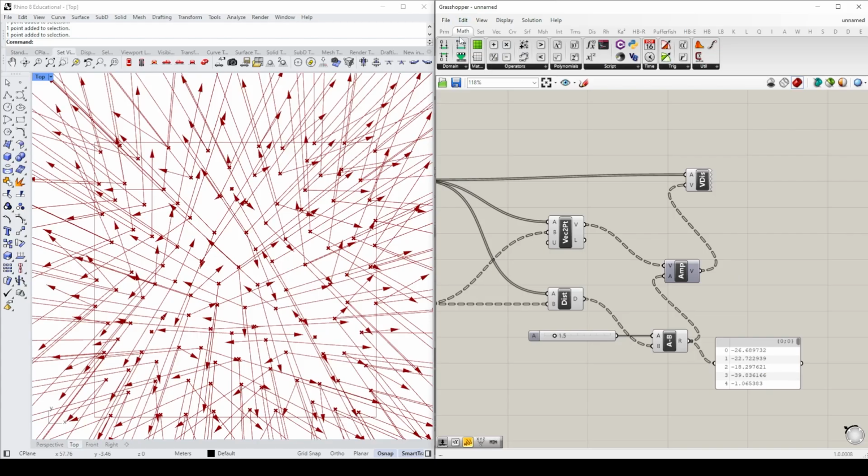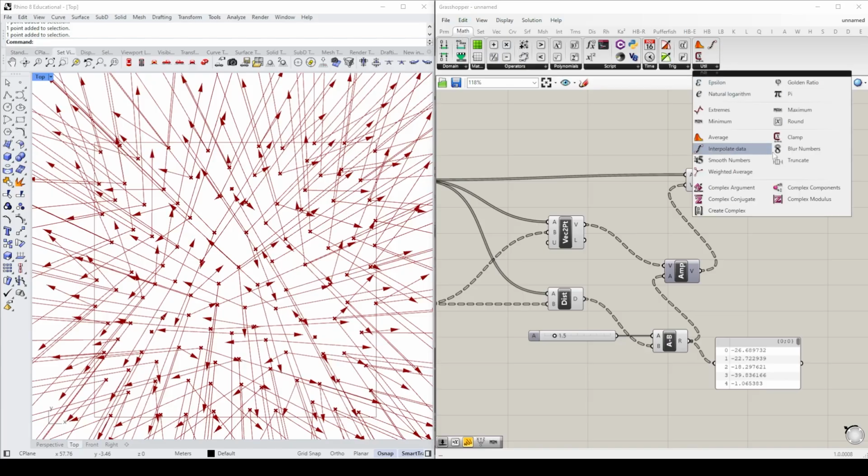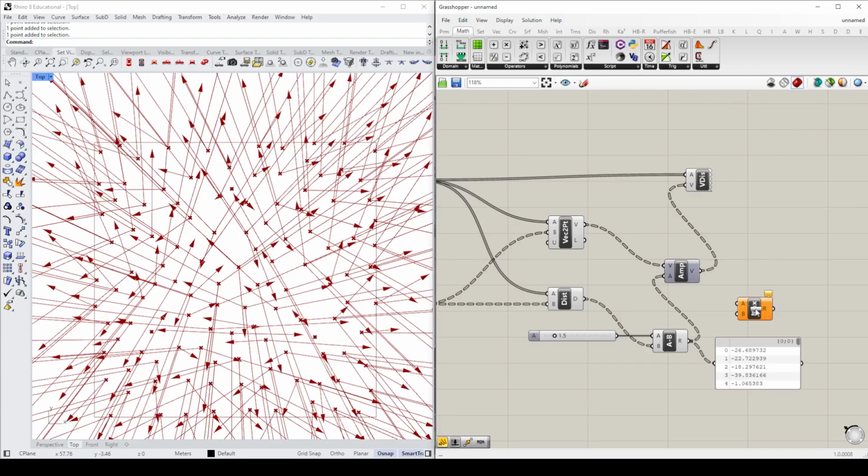I'm going to come here under the Maths tab, Utilities, and I'm going to put a maximum component. So what this will do is it'll allow me to return only positive values, and for input B, I'm going to drop a panel onto the canvas, so double click, double quotes, 0. So that will be my second value, and basically what this will do is it will return only positive values. Now currently, I don't have many or any positive values. We'll just put this into the preview.